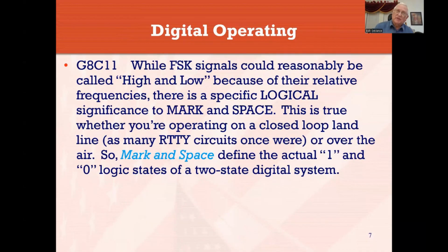I shouldn't say marking. That's confusing. It was spacing out over the time when nothing was coming in. And then when the data would start to come in, the thing would take off and start typing for you and the stuff would come out. But we use mark and space in the RTTY world. Mark is a 1, a space is a 0.